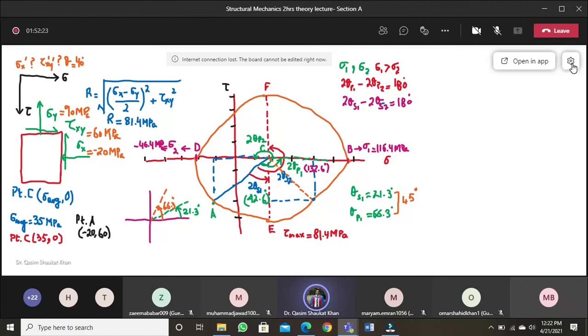So today we have done the Mohr circle. You have seen that the Mohr circle is a much simpler way of calculating. You can see the principal stresses, shear stresses, and orientation of the principal plane. Always remember, your reference plane will be CA. I will always move from reference plane CA towards CB and CD to get the orientation of the principal planes. You can also move clockwise, but then you have to mention that you are measuring clockwise; otherwise we assume counterclockwise, because that is positive.